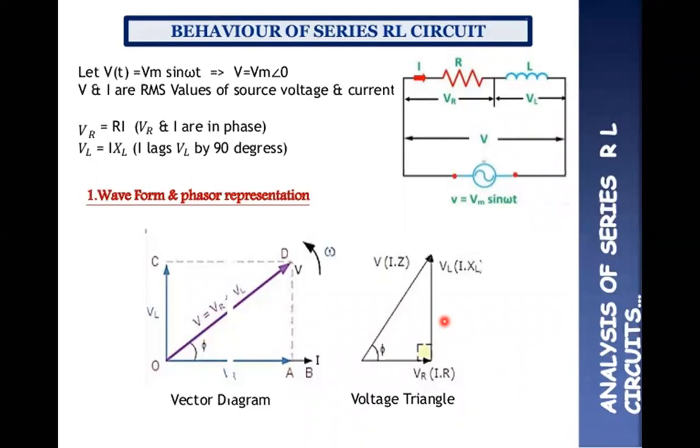In the previous slides, we have seen the alternating current passed through a pure resistor, inductor and capacitor individually. Now we will connect the resistor and inductor in series, pass the alternating current and understand the behavior of the circuit. Let us consider a circuit containing an alternating voltage V is equal to V max sin omega t, connected through a resistance of value R and a self-inductor of value L in series, as we can see in this particular circuit.